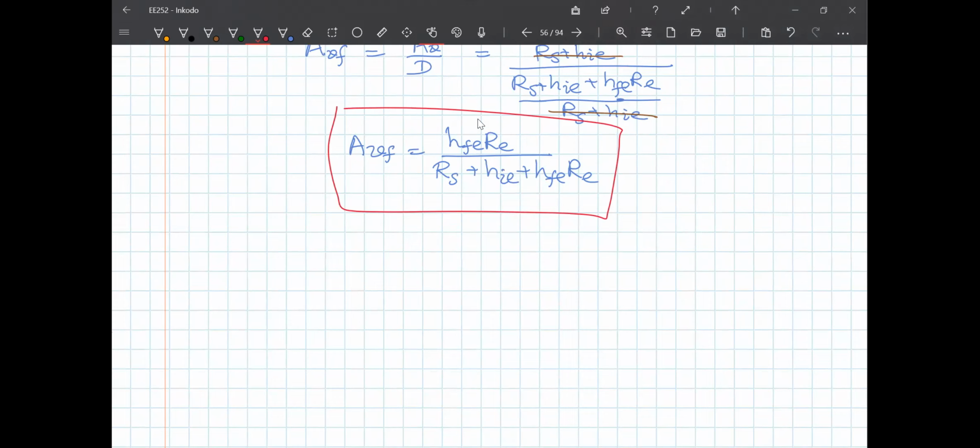It should be what? It should be equal to 1, right? Remember, for emitter follower, voltage follower, this voltage is the same in the base and the emitter, right? So therefore gain should be 1. Let's see if that is the case.